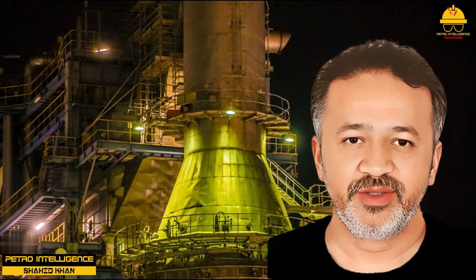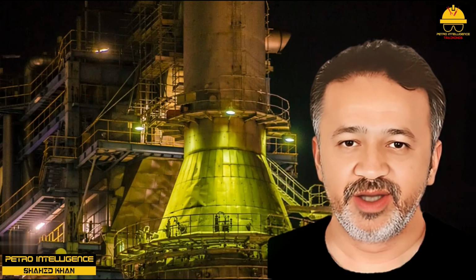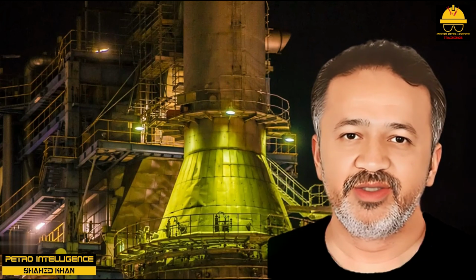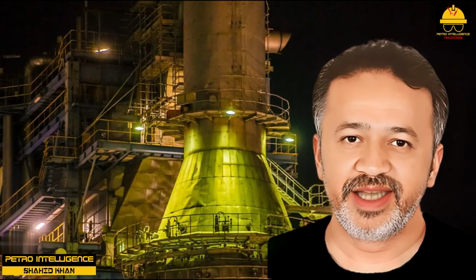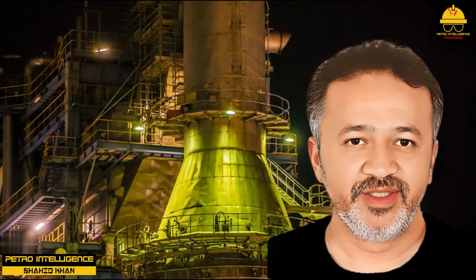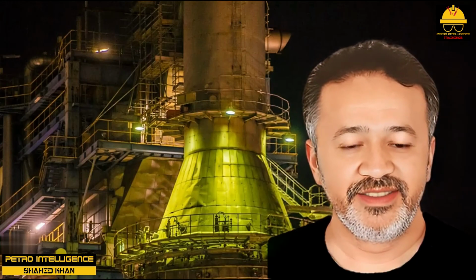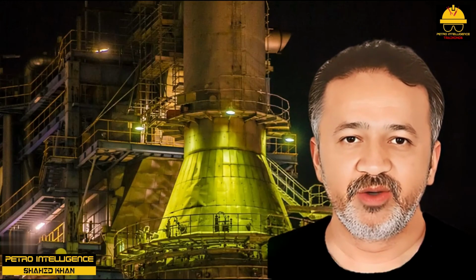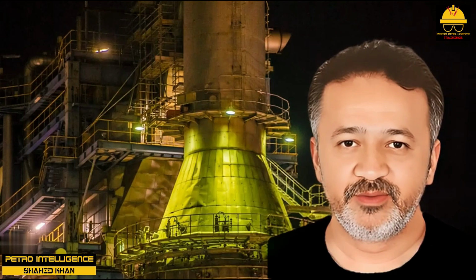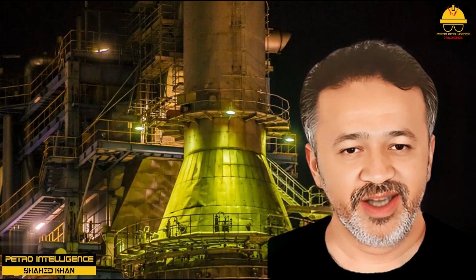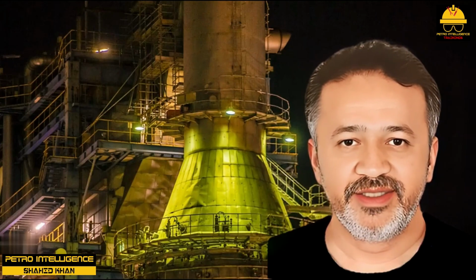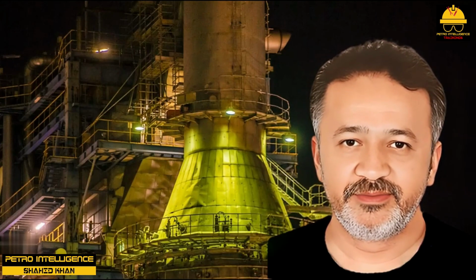This was a pretty accurate rendition of a discussion with two operators at the Tenneco oil refinery in Chalmette, Louisiana, in 1984. Today, burner manufacturers have access to all kinds of designs for pilot lights, to fit all shapes and sizes of burners and burner ports and draft systems, from the smallest breeze to gale force winds. There is no longer any excuse to operate without pilot lights installed and working.